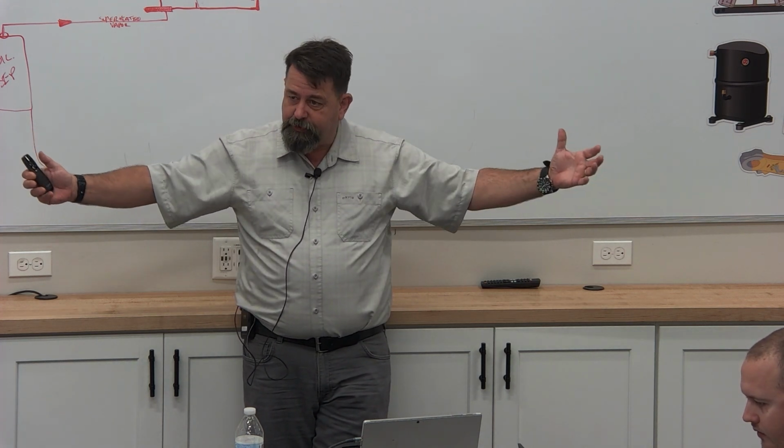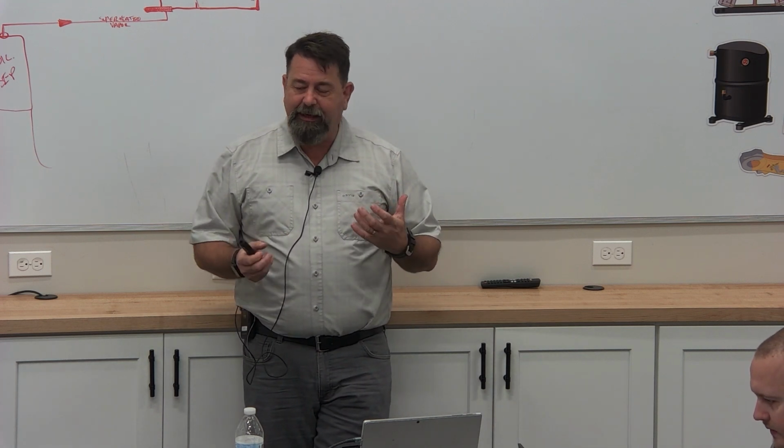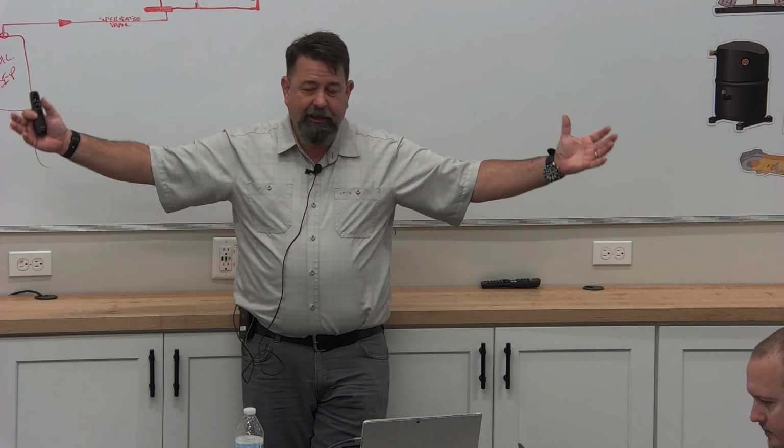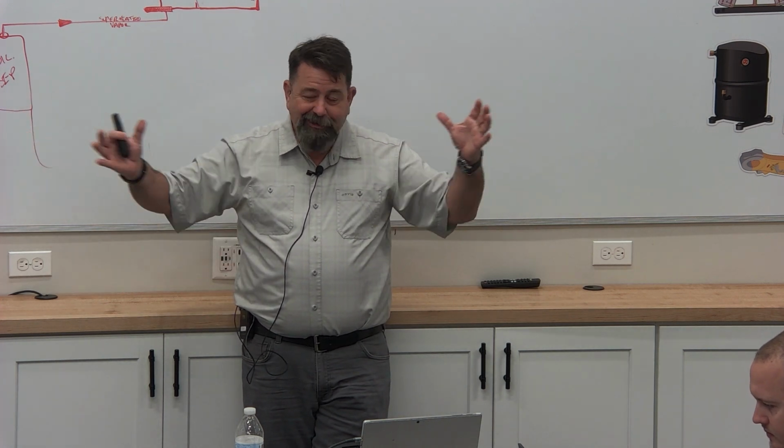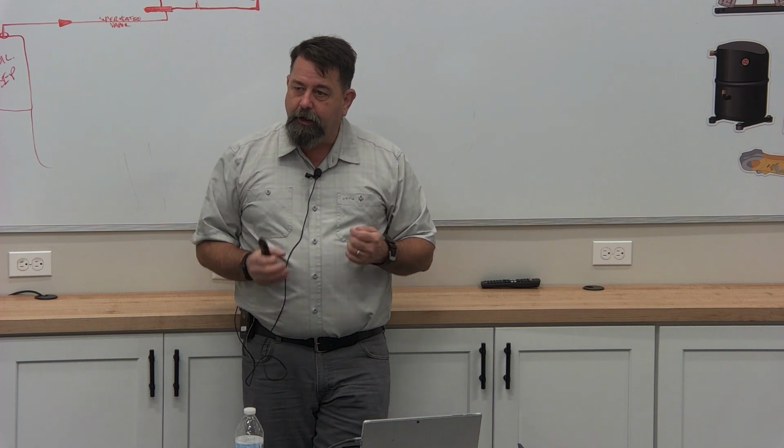So to do that, we want this heat exchanger, and that's what an evaporator is, a heat exchanger. It's exchanging heat from 2 different mediums, right? We want that to be large. We want it to be big so it can exchange a lot of heat. The challenge to that is it's wasted space. I can't sell product where I have this heat exchanger. It physically takes up space. So I want to be able to exchange that heat with a giant heat exchanger, but practically I need it to be small so it fits into a small space.